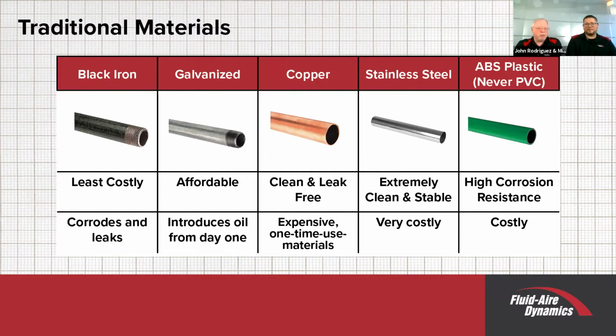Galvanized pipe is much less likely to rust. However, it can flake off. And again, you get the same issues, threading the pipe and cutting to length. Copper pipe, you have to cut to length. You buy fittings, whether soldered, which takes a little bit of time, or ProPress, something like that, and those fittings are very expensive. So copper, the material itself, is very expensive also.